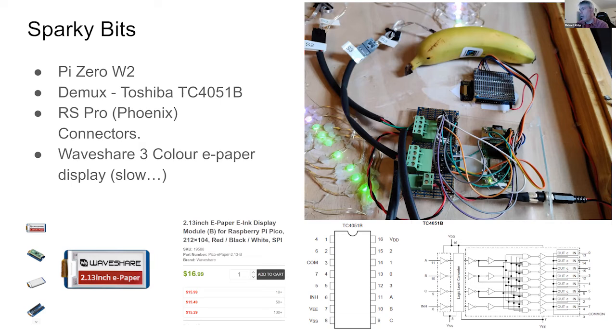Well, you're just sending a long string. If you've got 100 NeoPixels, you send 300 bytes of data telling it your RGB content for each LED. Oh, and it passes on to the next one and strips it. Is that what it does in normal NeoPixels, but these are special NeoPixels for God knows why. It surprised me a bit because I just bought them off Amazon, and then I realized looking at it now. It's very interesting.